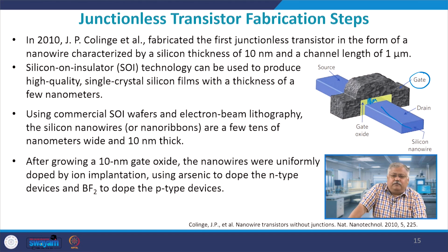Now, you have to be very cautious that the silicon nanowire should be very thin, because you want it to be inverted at a very low gate voltage, and the material quality used in the silicon nanowire should also be high, so that you do not have any traps or extra impurities being inserted within the silicon nanowire, right.